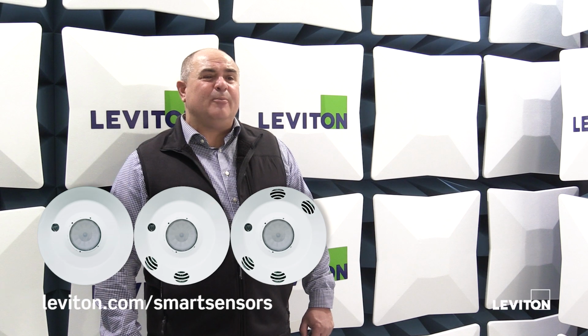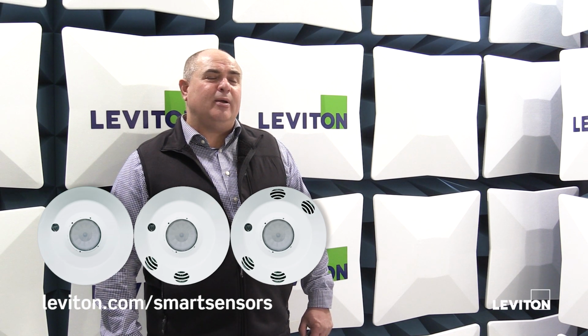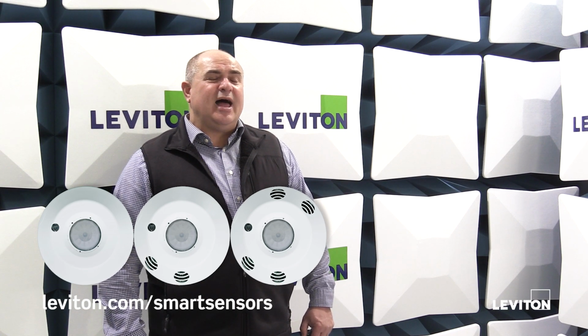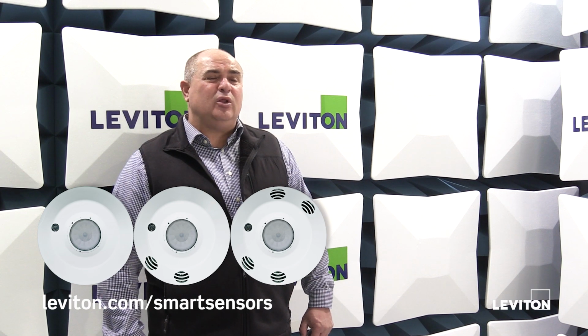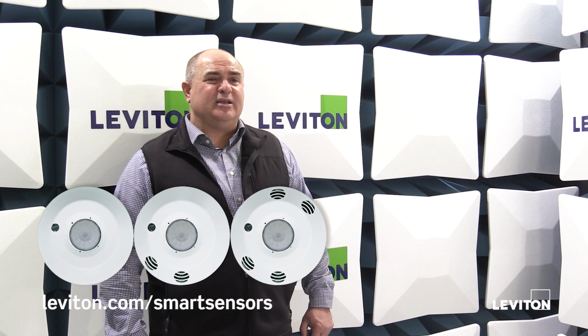What the angled light pipe will do as it's looking out the window is operate in an open loop manner, which will allow the sensor to adjust to the actual ambient light that is coming in through the window or other opening within the space.